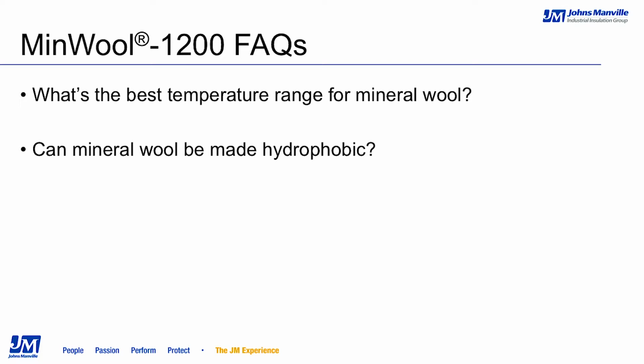And then 2, can mineral wool be made hydrophobic? Due to its porous nature, it cannot be made hydrophobic. However, there is a movement in the industry to lean towards water-resistant or water-repellent mineral wool, and it's something that Johns Manville is currently considering for its mineral wool product line.